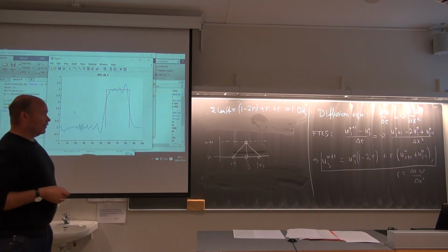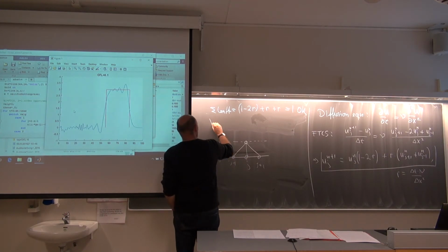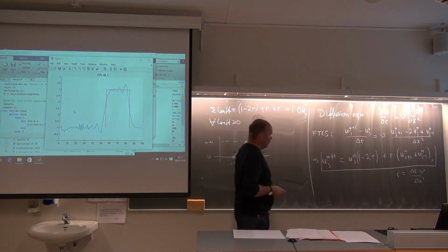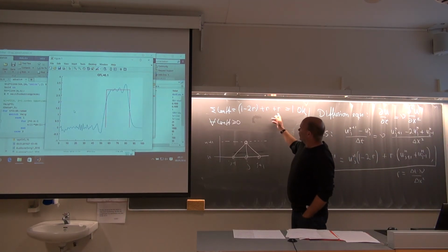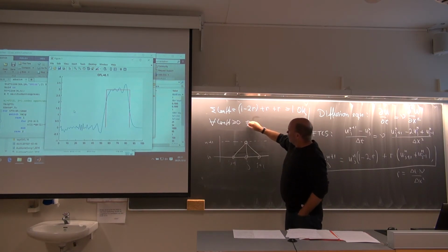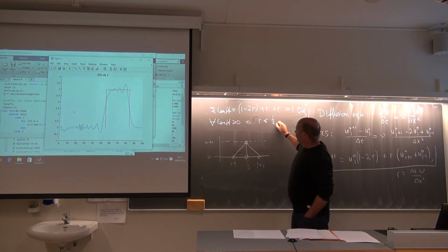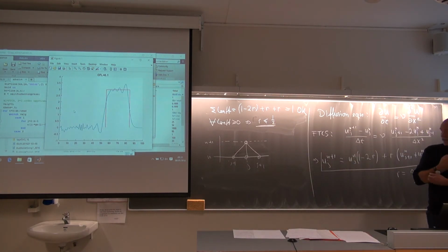So it's a very neat stability analysis, a very easy method. And now the criterion: all coefficients must be positive or equal to 0. Well, the r itself is of course a positive quantity. Positive delta t, positive viscosity, delta x squared is positive. So these r are not a problem. It's this parenthesis that has to be positive. So if everything is going to be positive, my r must be smaller than or equal to 1/2. This will be the demand for stability.